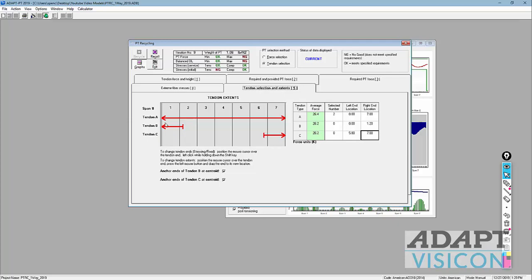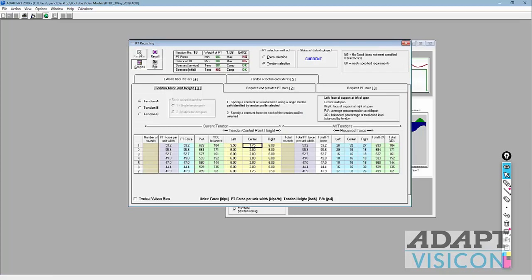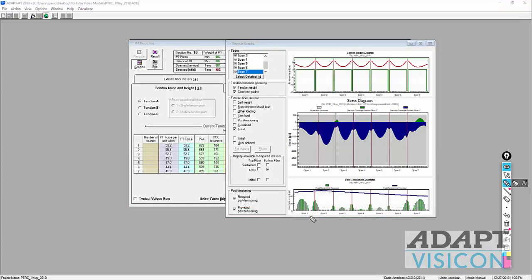and it's symmetric about the center of the tendon. We say, well, we're not going to have live-live. We want to have live-dead. So I'll use shift, change this to a dead end, and recycle. Okay, and now what we see is this type of profile. So this is a varying profile. We're losing force as we move from live end over to dead end. This is live to dead, and this loses force. The average of this curve is roughly 27.2 kips. So it's actually more than the assumed effective force of 26.7.